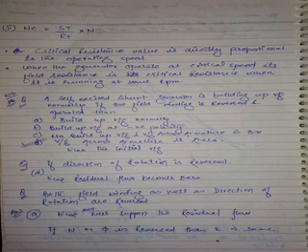What is phi? What is n? Phi is flux, n is speed. For one type of rotation you take plus, for the other rotation you take minus. For one polarity of flux you take plus; if you reverse the field winding, you should take minus. Previously either one is reversed, so there is a problem with the self-excited generator.